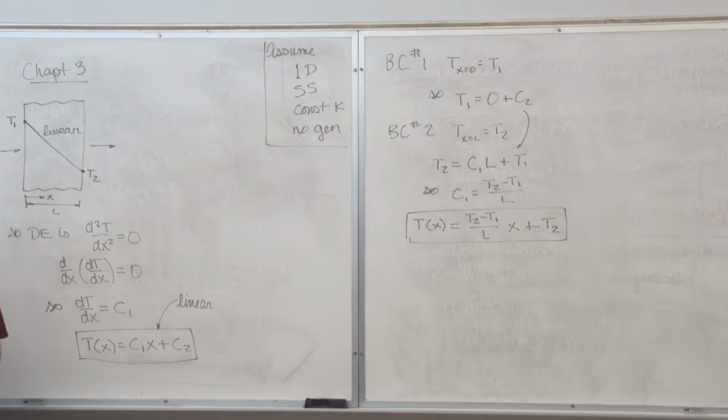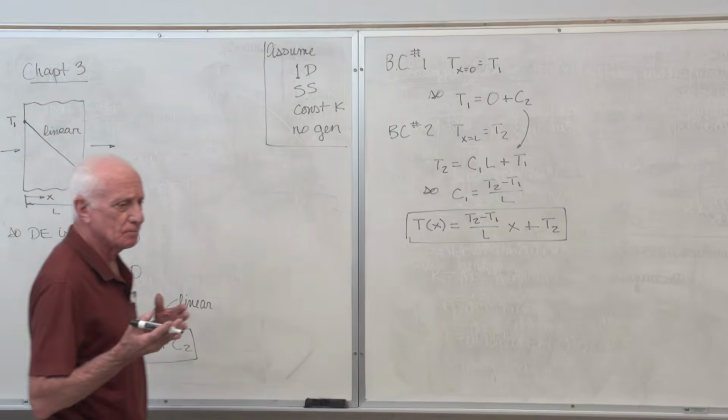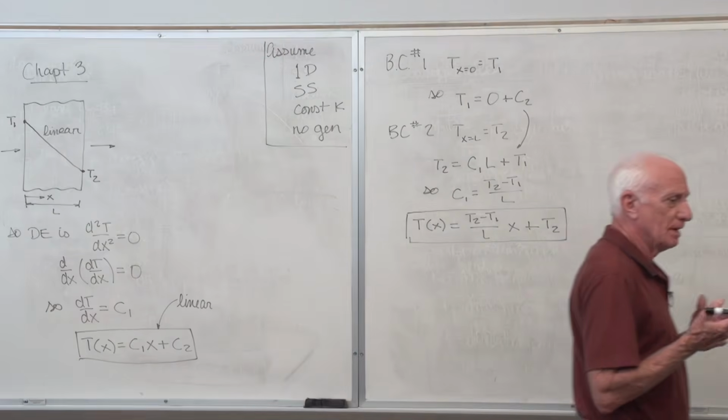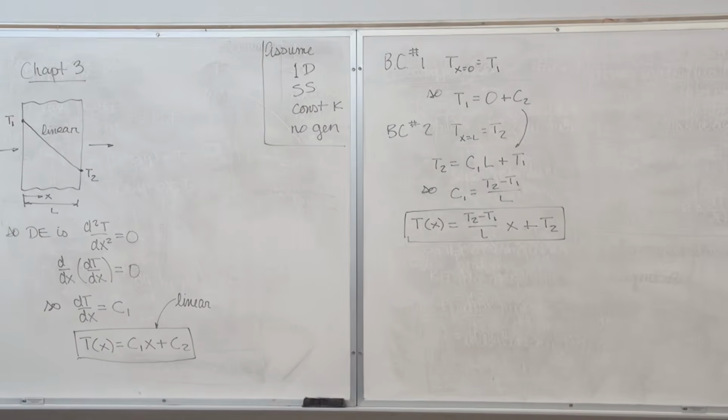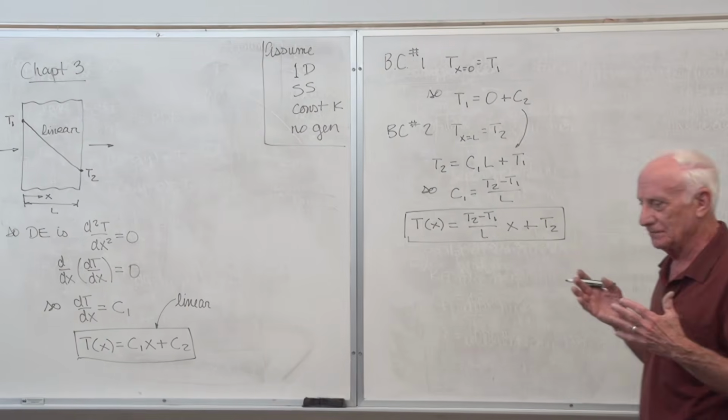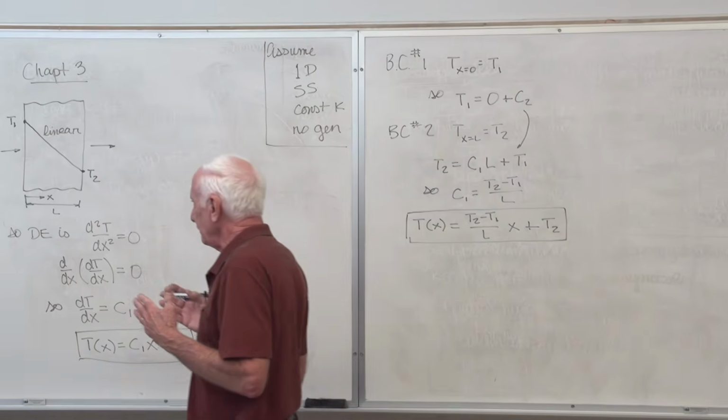Now that's the first object in a conduction problem, if you approach it from ground zero: you want to find the temperature distribution by solving the governing differential equation. Okay, but the real object is I want to find the heat transfer. Sometimes the temperature is important, for thermal stress problems and things like that, the maximum temperature in something you want to make sure you don't exceed. So it's important many times, but it's very important then, once you get this, to get the heat transfer. Okay, what's the heat transfer?